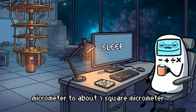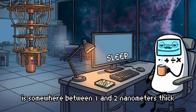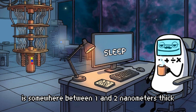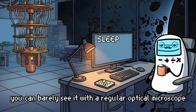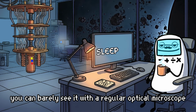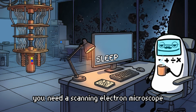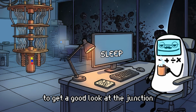The junction area is typically on the order of 1/10 of a square micrometer to about 1 square micrometer, and the oxide barrier is somewhere between 1 and 2 nanometers thick. You cannot see it with the naked eye. You can barely see it with a regular optical microscope. You need a scanning electron microscope to get a good look at the junction.